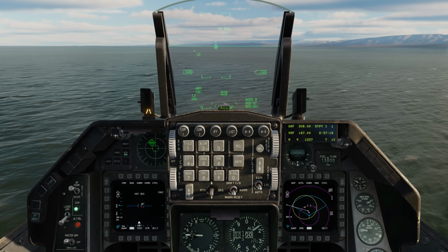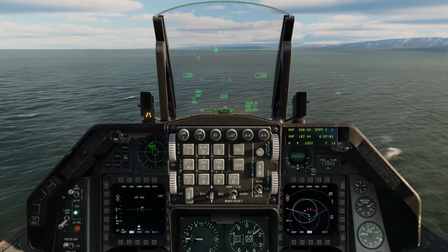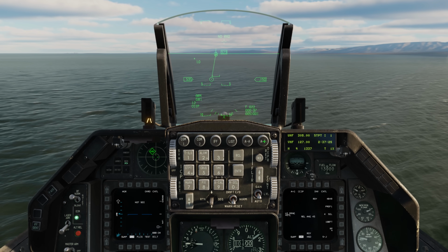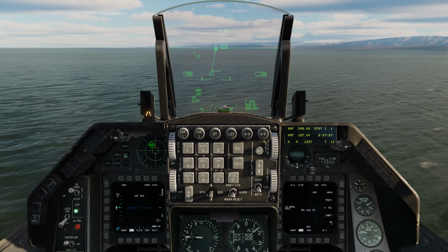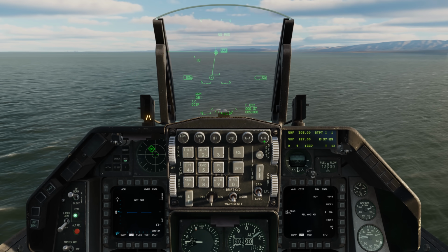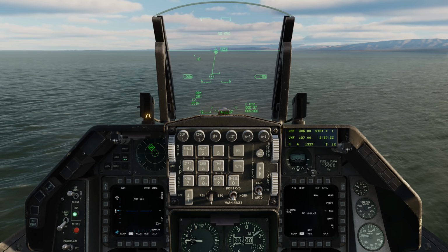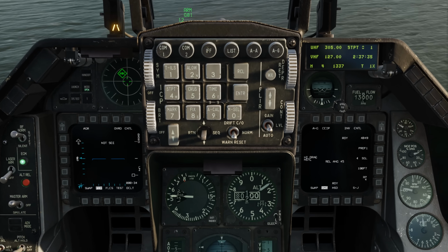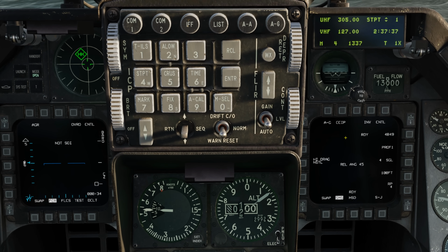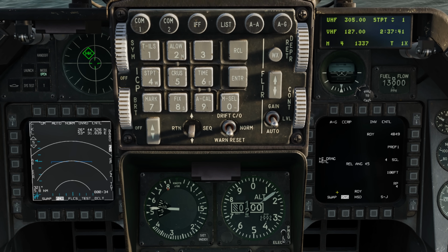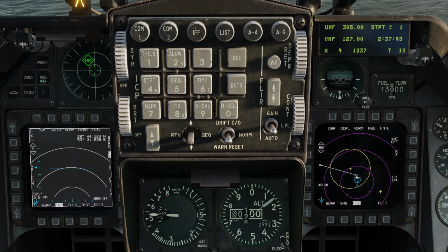So right now I'm in active pause mode, and let's set up the jet. First we're going to go to an air-to-ground master mode up here on the ICP, and we'll want to be in CCRP mode or related, like dive toss or LADD. And to do that, of course, we can cycle the nose wheel steering button, or we can come down here to the SMS page, go to bombing modes on OSB 2, and select CCRP. Let's bring this to HSC now.